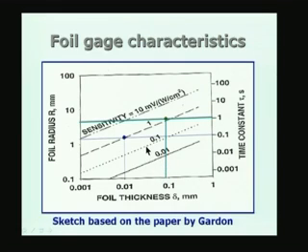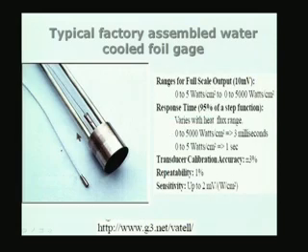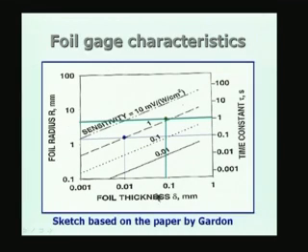And I have also taken another example here. If I take a foil of 0.01 millimeter thickness, incidentally this is in millimeters, this is also in millimeters, both are in millimeters. So, you see that a foil with 0.01 millimeter thickness with a radius of slightly more than 1 millimeter also gives the same sensitivity. So, sensitivity can be obtained for different radius delta combinations, and let me just digress a little bit and see why we should have different radii and different thicknesses.